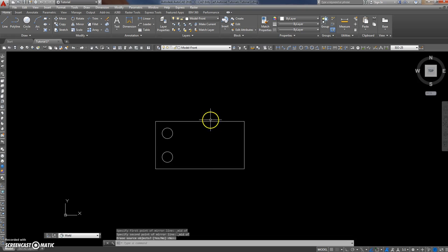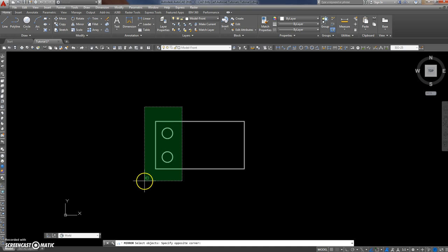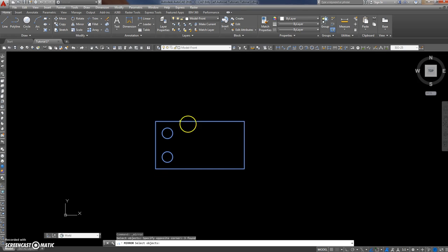Okay. Now here we are going to use a different way of mirroring. We're using these things here, and we're going to mirror about just one point only. So we use the mirror command again. Now here's a word about selection with your box. If you pick here and drop down to there, you'll notice that you're picking everything. That's called a crossing window, and you don't want that.